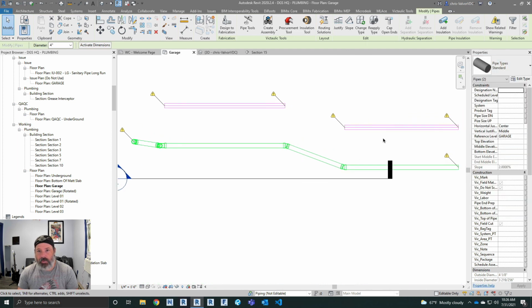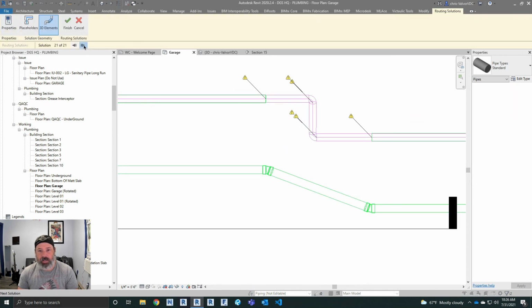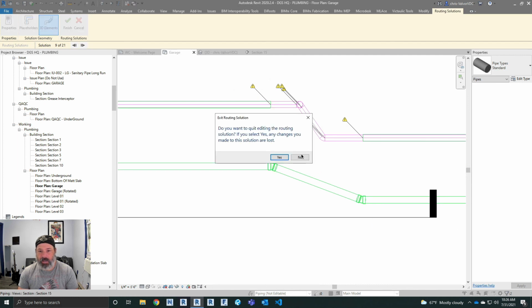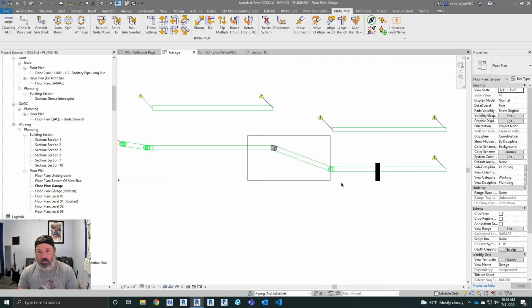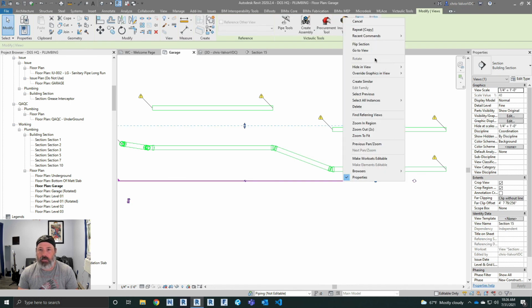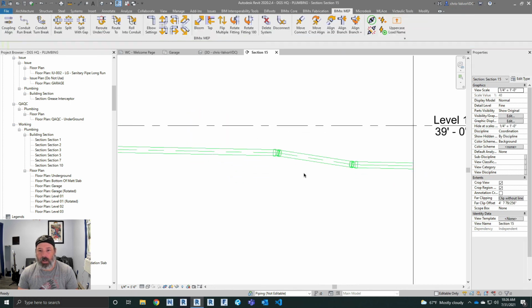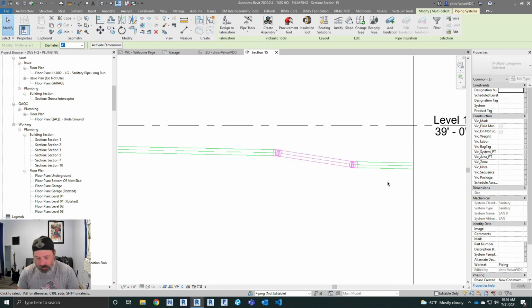Out of the box with Revit, if you use their standard routing, you get this. You can tell that's a 90, but you have no idea what the rest of this stuff is. You can take that guess, and then it starts getting T's in here, and that's something I want to talk about next. Are these T's that you get? This works really good if you're about 6 to 8 inches up, anywhere between 1 and 6 to 8 inches up.